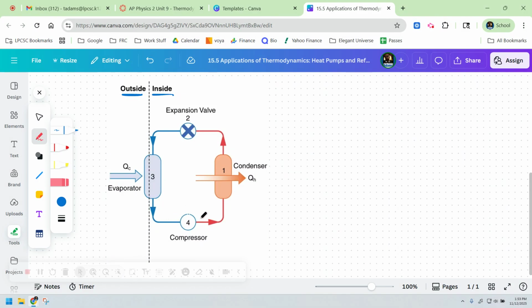The compressor will change the pressure. The condenser does its part, but it also extracts the heat out. That heat gets absorbed by the fluid, and then the fluid transfers it to an expansion valve, and then the process repeats, okay? And so what's really going on is the electrically driven compressor does work into the system. All right? So again, I'll write this formula down again so you know that the high heat is equal to the cool heat plus the work. Okay?